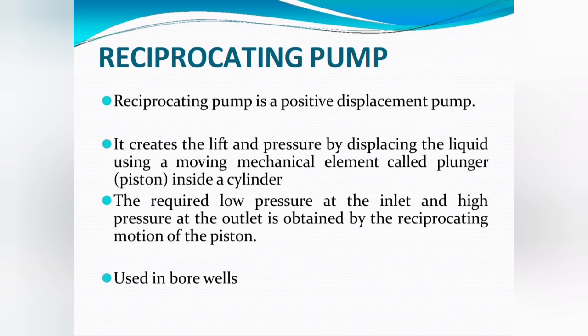It creates the lift and pressure by displacing the liquid using a moving mechanical element called plunger or piston inside a cylinder. The required low pressure at inlet and high pressure at outlet is obtained by reciprocating motion of the piston. It is mainly used in bore wells.